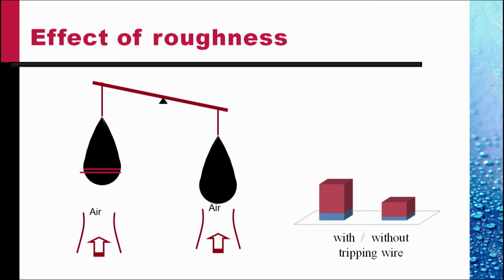So, as the flow changes from laminar to turbulent, the decrease in pressure drag is small because the drag is itself small, but the increase in viscous drag, the shear drag, now dominates. The shear stresses in turbulent flow are much more, so the shear drag increases, and since it is dominating,